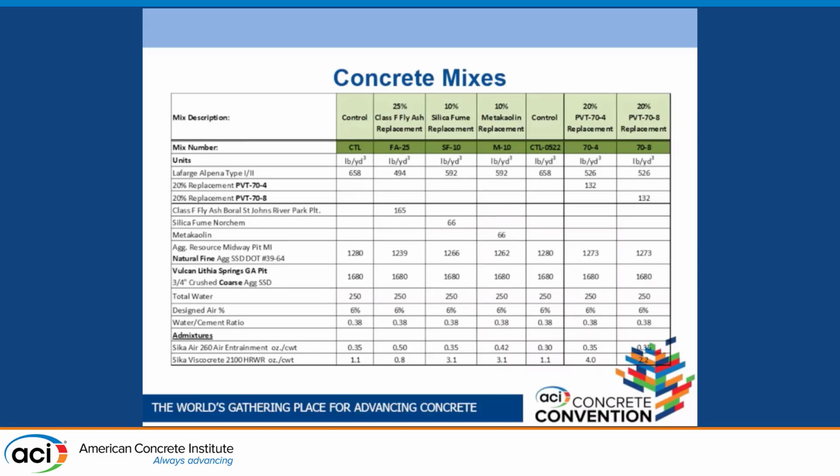For the concrete mixes, the last stuff was done at the standard ASR test water cement ratios. The concrete was done at a lower water cement ratio. These are durable concretes. Mixes like this are used on some monumental bridges, maybe a little bit less water, in some cases a water cementitious ratio sometimes lower. But this is like the ballpark you need to be in, and we're going to use this later on. We'll show you for modeling.